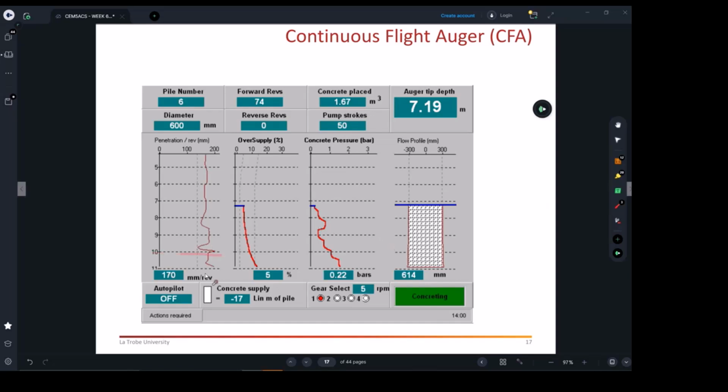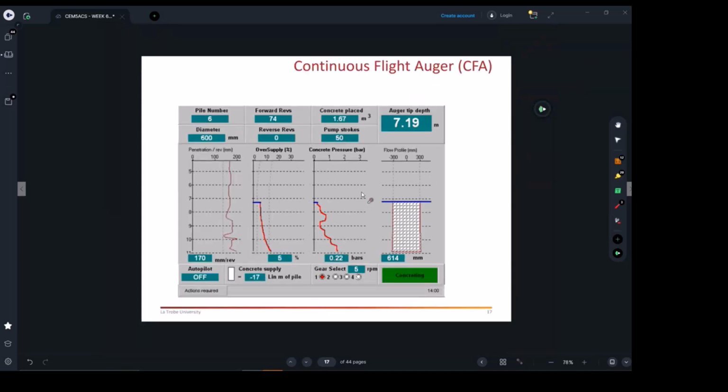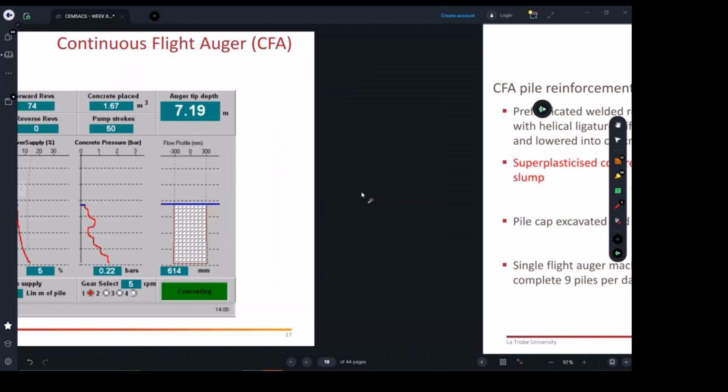Maybe it was 10 meters, but here they started from 11, which is more than required. And there is always pressure on the sensors or on the tip of your auger from the concrete, and the diameter to be within the acceptable limits. That's basically what reporting data should be observed.